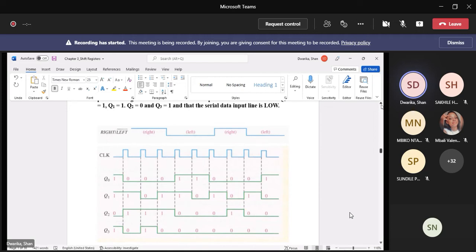Okay? And you can see then the 1101 goes down to 110, okay? And obviously on the top it will be 0, right? If you shift that again further to the right, on the next clock pulse, the 11 is shifted again, so you get 00 on top, and you get 11, right? And the third one also does the very same thing.